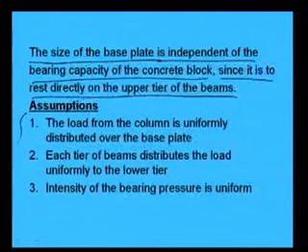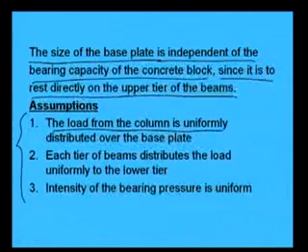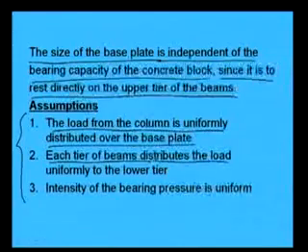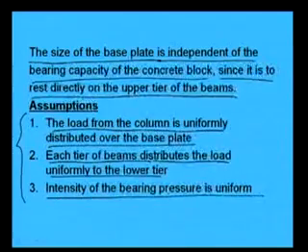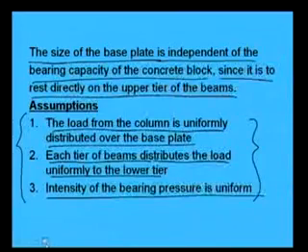Now, the assumptions we consider for designing the grillage foundation are, first, that the load from the column is uniformly distributed over the base plate. Second, each tier of beams distributes the load uniformly to the lower tier. Third, the intensity of the bearing pressure is uniform. These are the three assumptions based on which we are going to analyze and design the grillage foundation. Now, first let me show how this grillage foundation looks.